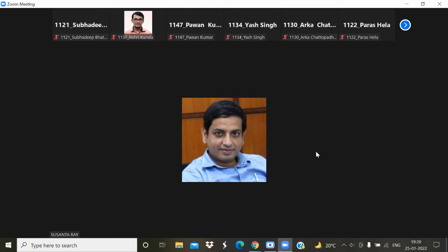Kw value you can take 0.95 or 0.955 or 0.96. This type of value you can assume for winding factor Kw. Average flux density you take 0.4 to 0.6, as I already mentioned in the last class. B average 0.4 to 0.6 Weber per meter square.